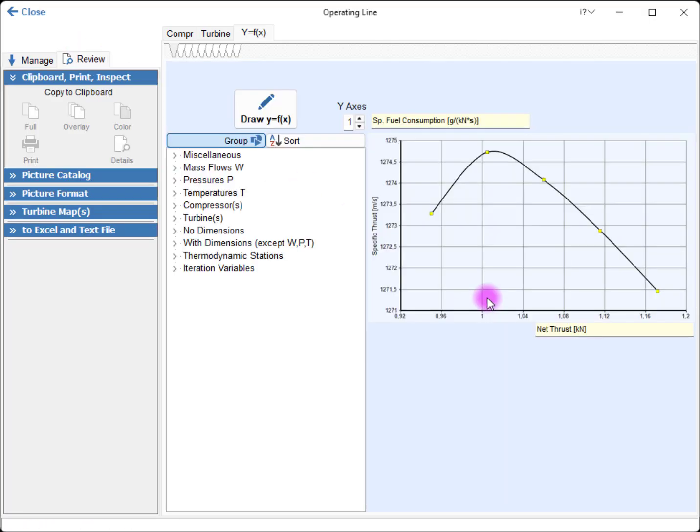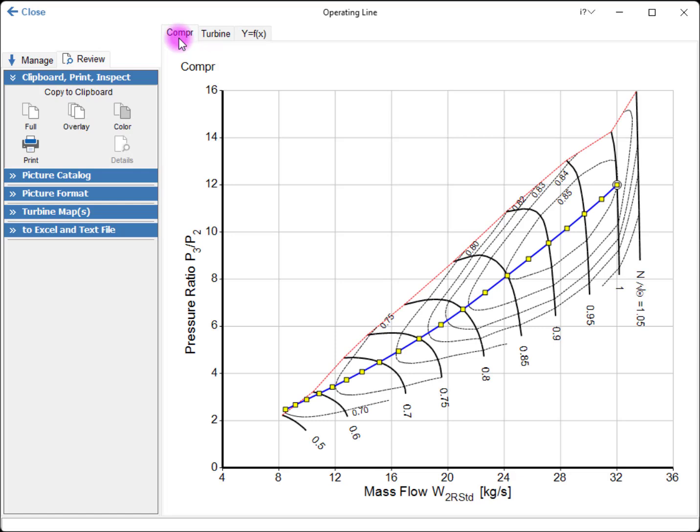We open the compressor map. The operating line of the compressor is displayed as defined before with 20 points and a step size of 2.5% of the relative spool speed. At low part load, it becomes obvious that the compressor is in danger of surging. In order to cure that problem, we will employ a handling bleed.